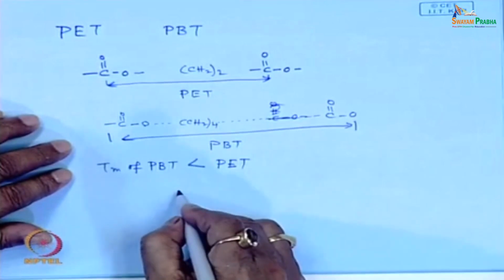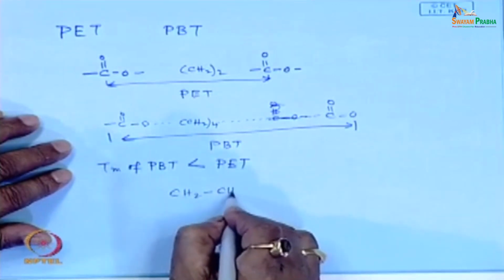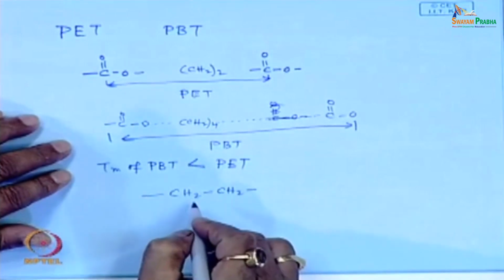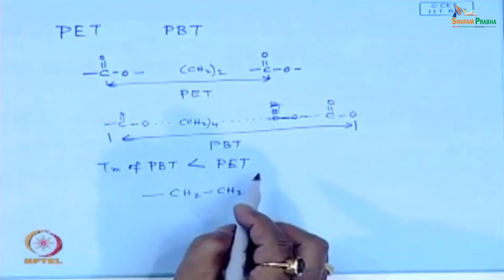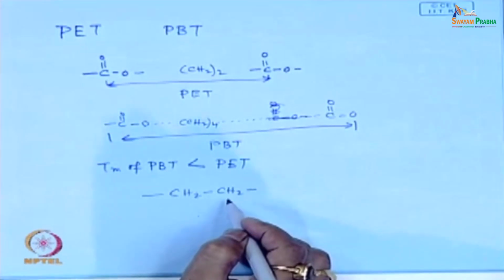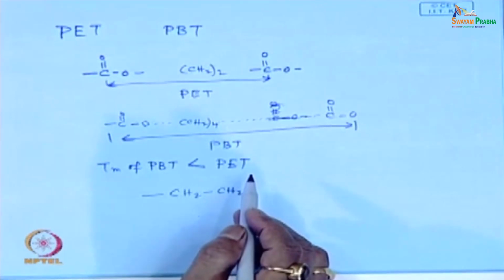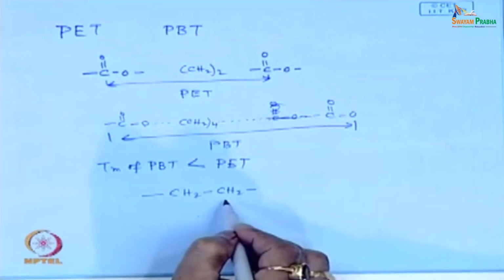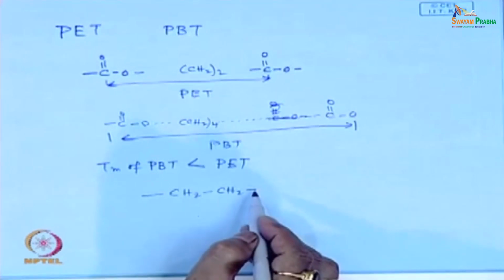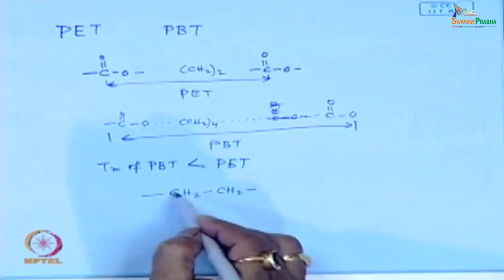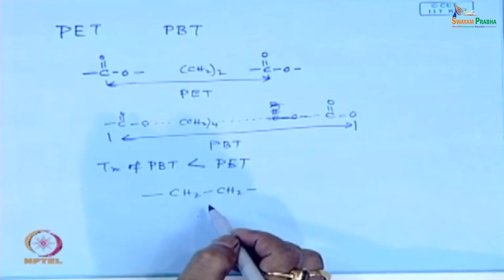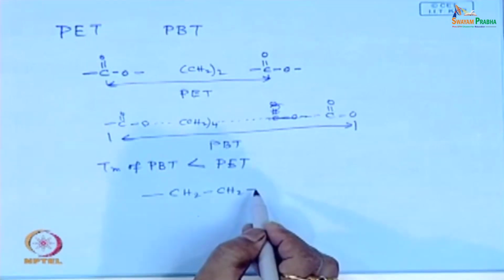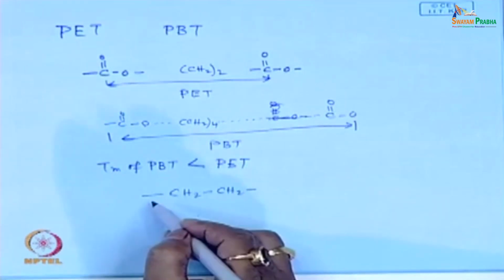Similarly, simply polyethylene is also flexible, and this flexibility is related to its glass transition. I will discuss what glass transition is later. So, polyethylene is flexible, but its flexibility is a little restricted due to close packing of the linear chain molecules because of the size of the hydrogens attached to carbon.